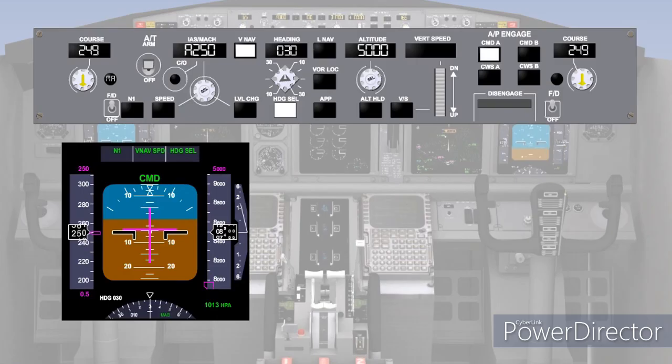At the required altitude, the aircraft will level off as the autothrottle takes back control of the speed, and the pitch channel of the autopilot maintains the altitude. The flight mode annunciator changes autothrottle to speed and pitch to VNAV path.